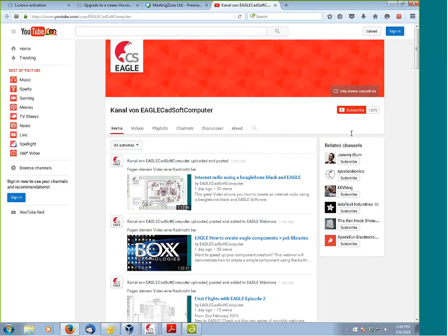Default way of creating Gerbers for all PCB houses, 274X. Okay, so Charles, the procedure I went through now for the Gerbers, that works for all board houses, okay? That works for all of them. Those who have worked with Eagle before will recognize the extensions, so they may not ask you what each file represents. However, if you go to a board house that doesn't deal with Eagle very often, they may ask you to specify what each extension means.